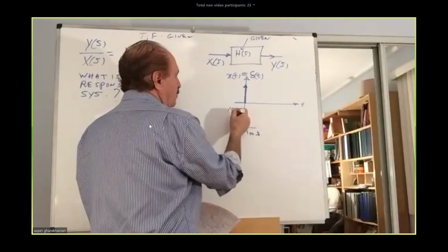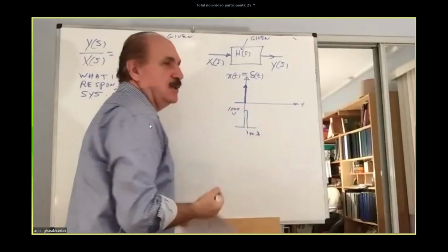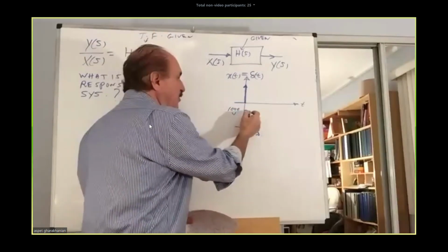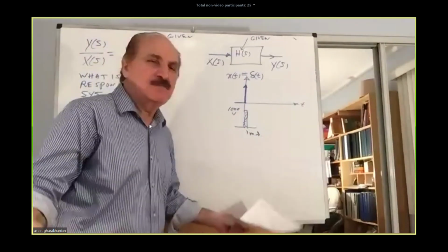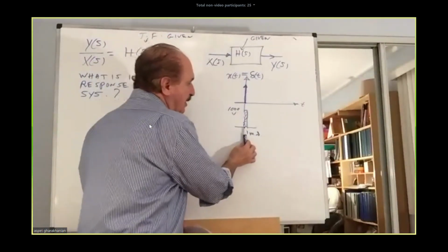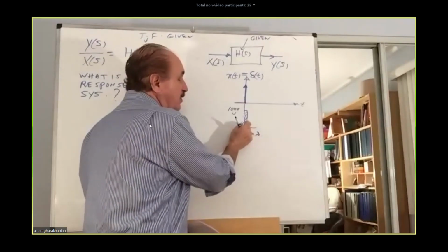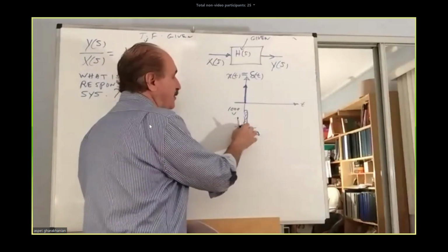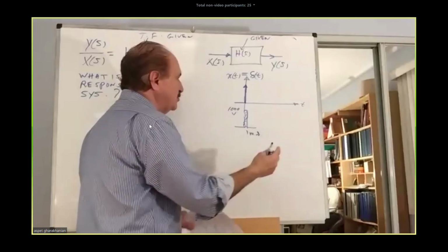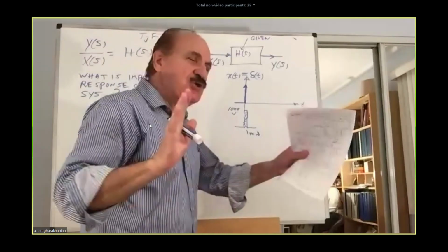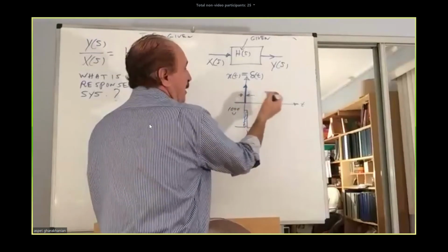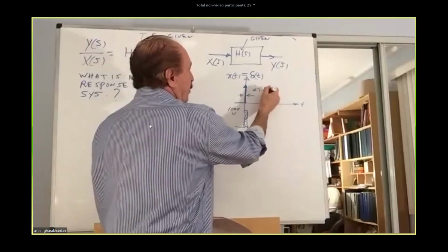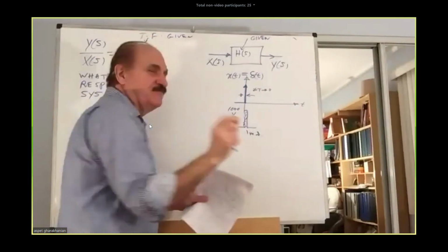1000 volt, 1 millisecond, this could serve in the analysis of the system almost like an impulse, because its timing is very, very small compared to the time constant of the system. So it will be considered that theoretical delta t approaching 0, because it is narrow.